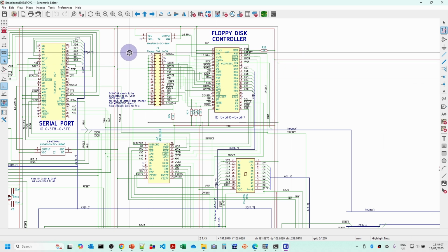So just going to program the PLDs and then start wiring up the board. Now the BIOS already has most of the changes we need. The only thing we really need to do is to make sure that we enable the Diskchange support. So I'll do that and program that, and then when we come back we should be ready to see if we can actually access a floppy disk.